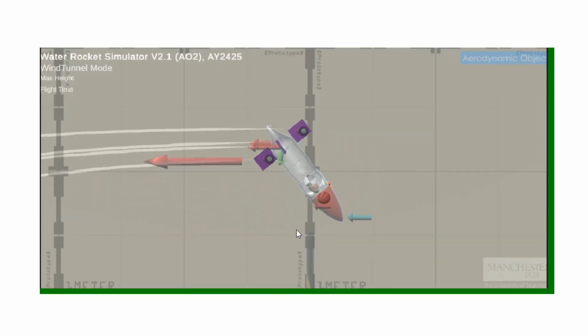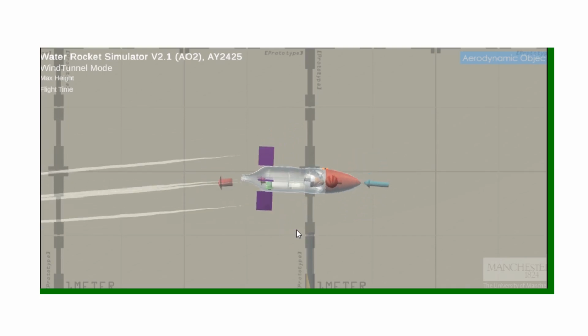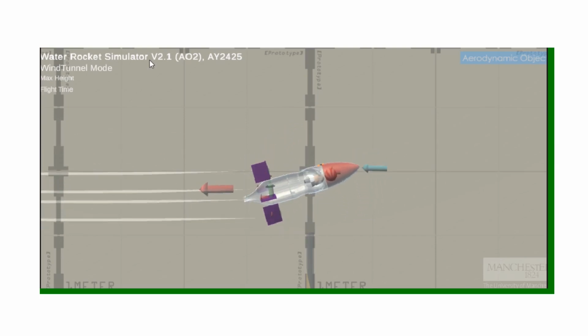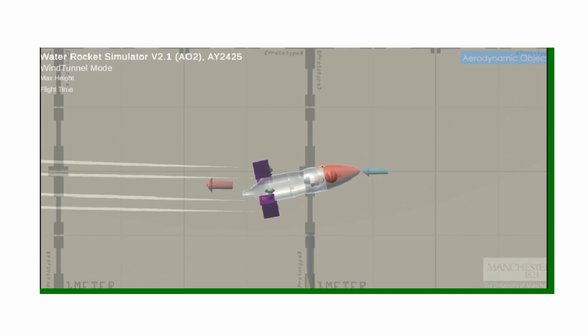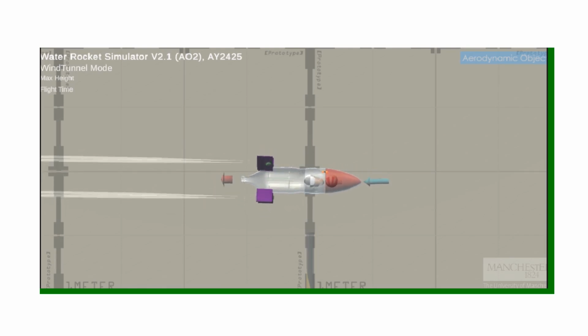We decided for this design to have fins in the bottom, as this puts centre of pressure below the centre of mass. As a result, this will increase stability in the perpendicular axis and it will return to equilibrium much faster.